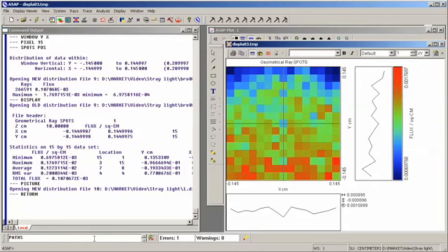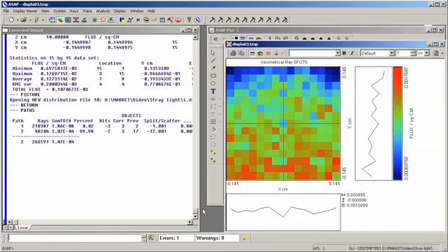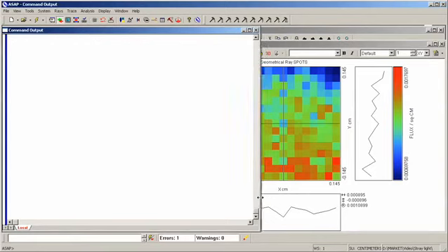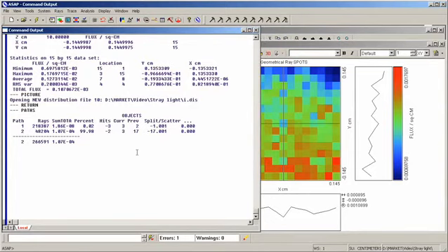That is to say, we issue the command paths, and ASAP prints out a table. It's a numerical table that's relatively easy to import into a spreadsheet, but it tends to be just a little bit cryptic. Here's the basic idea. ASAP is telling me that for this stray light calculation, only 2 stray light paths were found. The objects that scattered the rays are given a number. It turns out that the very first object in my model was the primary mirror. The inner conical baffle is the 17th object for my system.